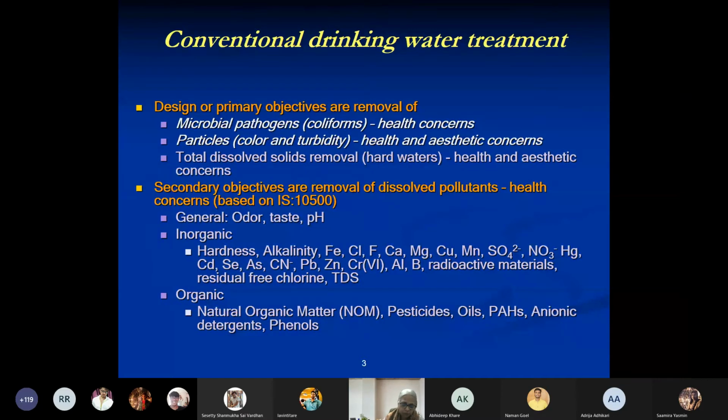If you have very hard water, let's say something with more than 500 milligrams per liter of total dissolved solids, then one, you won't like the taste. It tastes saline, so most people will reject it on that basis. That is the first thing. The second thing is you will get precipitation of calcium and magnesium when the concentration is high, and again that becomes partly an aesthetic issue.